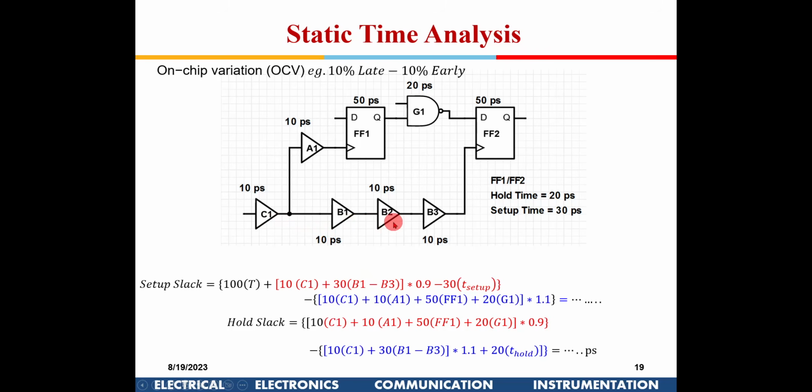So I have one clock, two clock here, one buffer, 4 buffers, right? And I am not applying that on the hold time, because for this particular problem statement they have asked us not to apply OCV here. If it says apply here also, then this also goes into this bracket. So now you will get slightly lesser hold slack. There could be a violation also, I'm not sure. You have to do the calculations and see. So this is how we apply these OCV variations.